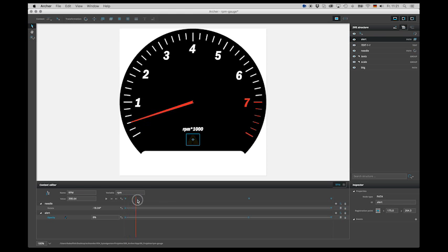Archer automatically applies a linear interpolation to the values from one boundary to the other. So here the opacity will automatically rise to 100% when you have 4800 RPM. That is not really what we want. We said that the alert sign shall appear at 4800.